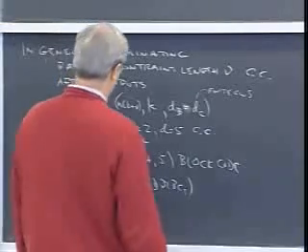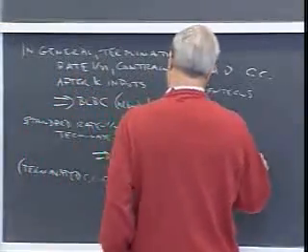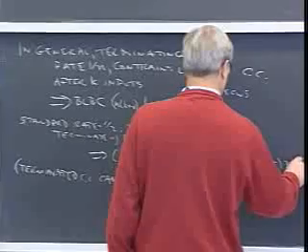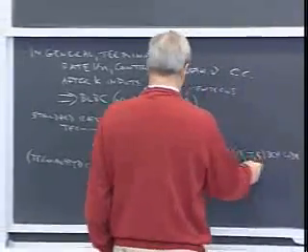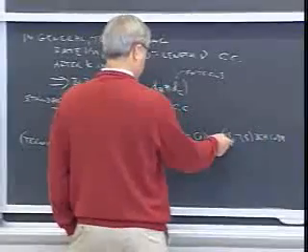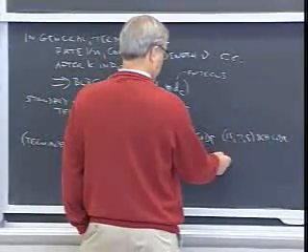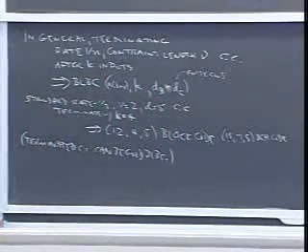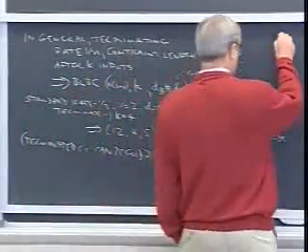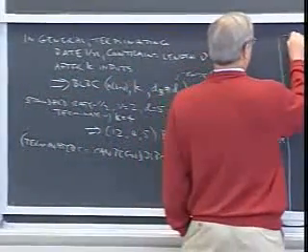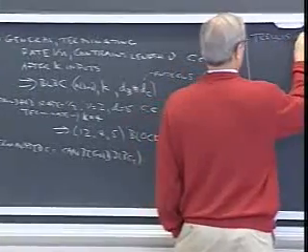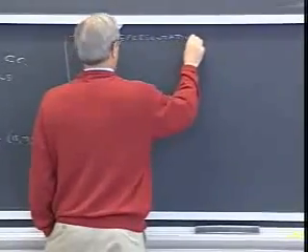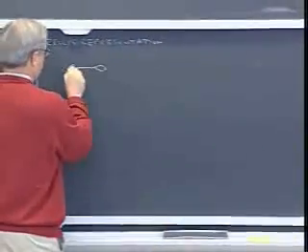You might compare it to what? The BCH code. There's a 15, 7, 5 BCH code, which is clearly better because it's higher rate. But if you shorten this code, you have to shorten this by 3 to keep the distance. You would get this same code. So, it's not optimum, but it's not too bad. And furthermore, from this construction, you get a trellis representation, which in this case would look like this.